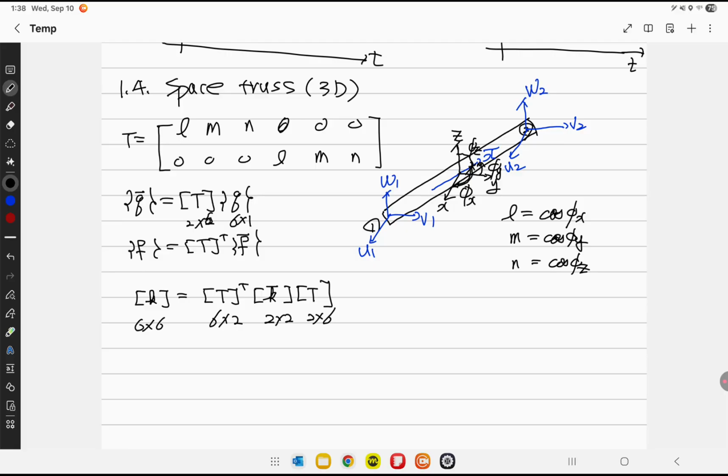Any question? Yes. Are those angles all still measured in a right-hand sense about x or y? From positive x to the local x bar, from positive y to the local x bar, positive z to the local x bar. Always positive global to positive local. In the first row, fourth column, that should be here. Maybe I wrote it the wrong way.